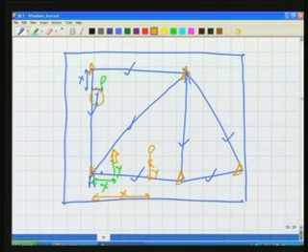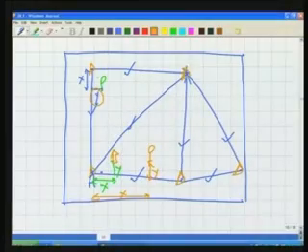Again, this is an independent plot. So this particular plot does not affect at all the accuracy of this plot. We may be slightly wrong in measuring this, but it is not going to affect the rest of the map. So our errors are not going to accumulate, they are not going to add up.